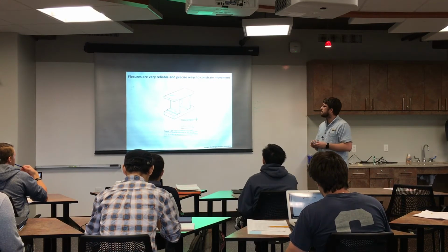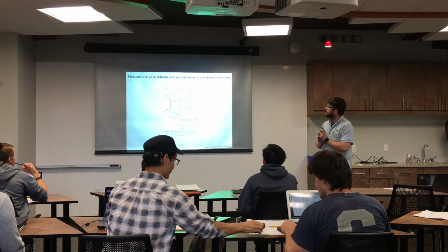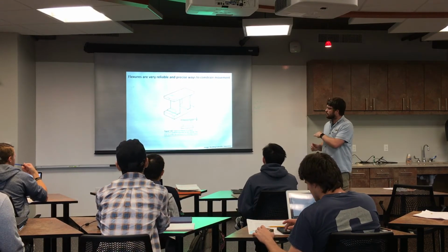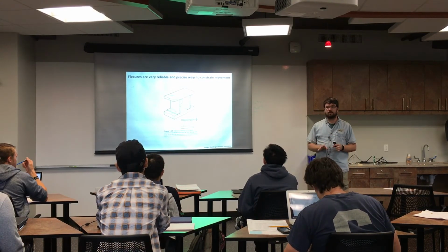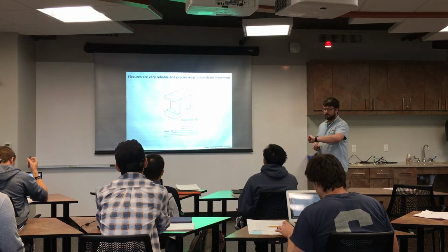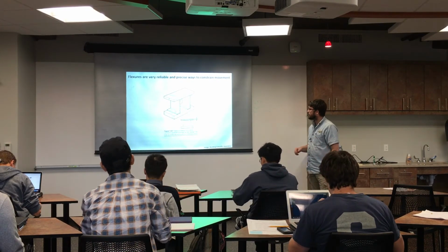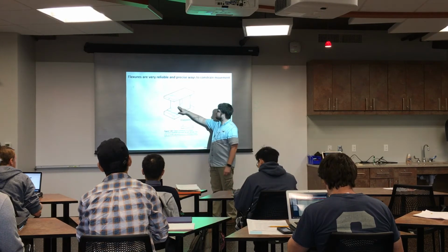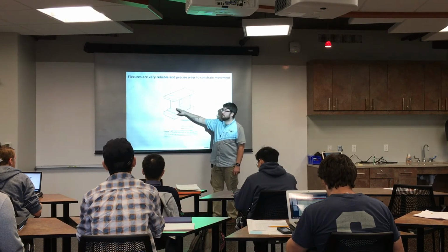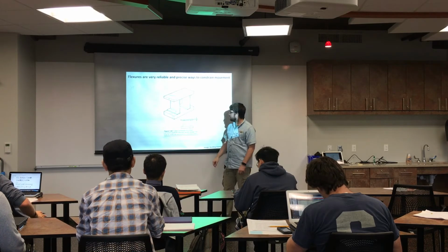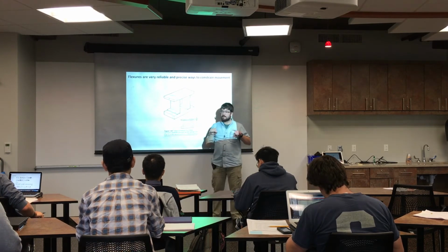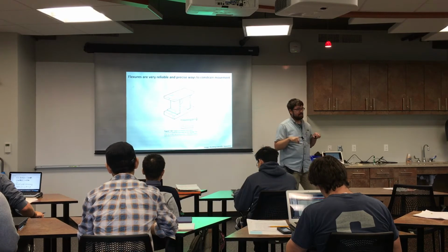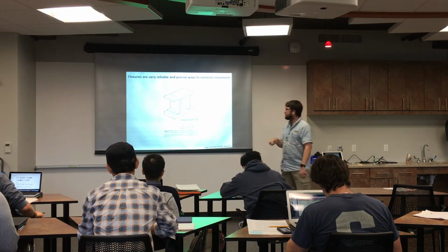Okay, so flexures are a really nice way to constrain movement. And I'm going to show you a video on this in just a second. Actually, we're going to watch like 4 or 5 minutes of this video, see how the time's going. But a flexure is you have these bendable elements. So here we've got 2 plates and 2 bendable elements that are, let's say, riveted in between there. And so if you push on the top plate, those are going to bend, and it's going to translate in one direction only. So we're constraining it to 1 degree of freedom.